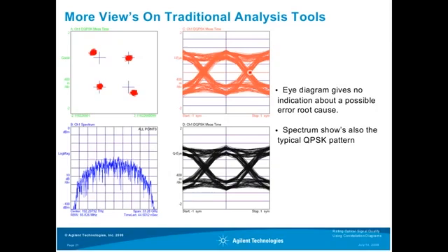So I think now it's time to introduce the error vector concept. Here again, we have our constellation diagram as already described at the beginning of this webinar. You can see our ideal constellation point represented by the amplitude and the phase of the signal. But the world, as we all know, is not perfect, and we would probably measure this constellation point instead of this point.